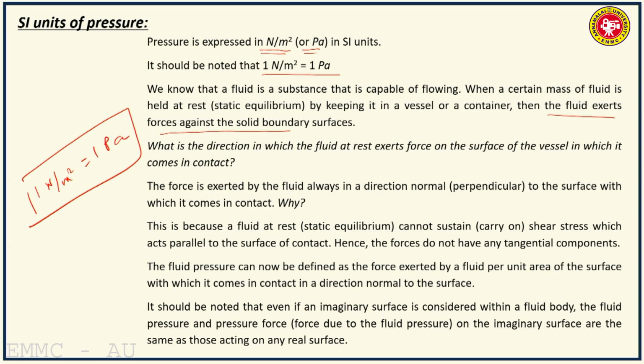Now let us discuss the direction in which the fluid at rest exerts force on the surface of the vessel with which it comes in contact. What is the direction of this pressure force which is exerted by the fluid on the surface of the container? Now the force is exerted by the fluid always in a direction normal, that is perpendicular, to the surface with which it comes in contact.